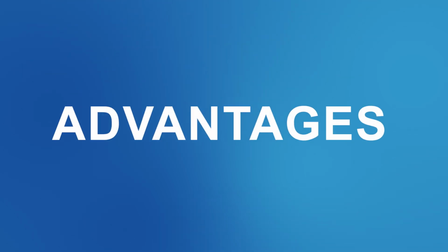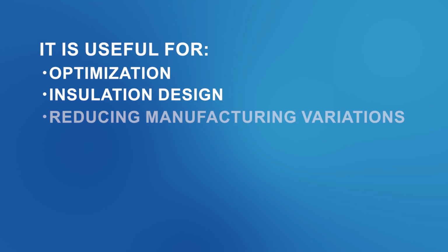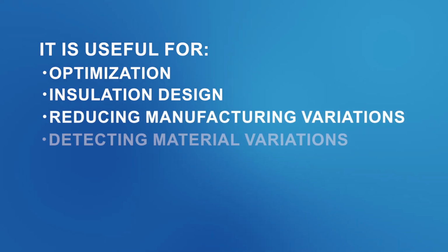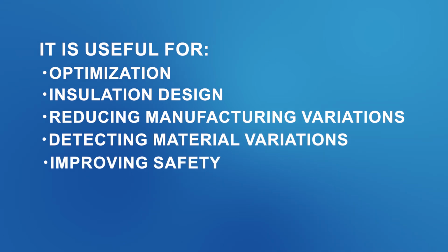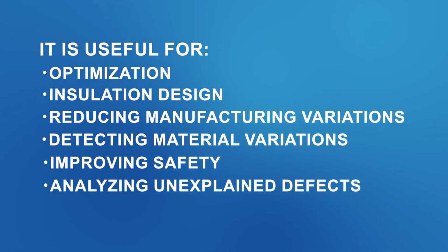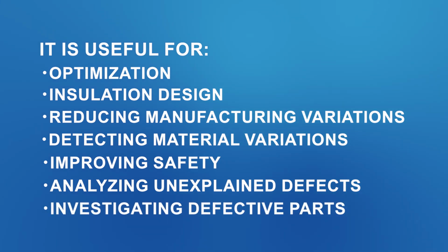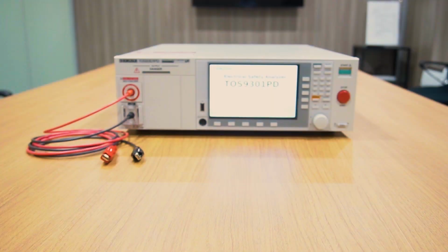Furthermore, the following advantages can be expected compared to conventional methods. It is useful for optimizing insulation design, reducing manufacturing variations, detecting material variations, improving safety, analyzing unexplained defects, and if defects can be detected non-destructively, investigating defective parts becomes possible. Now, let's see some actual partial discharge.